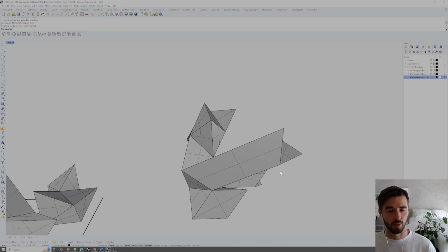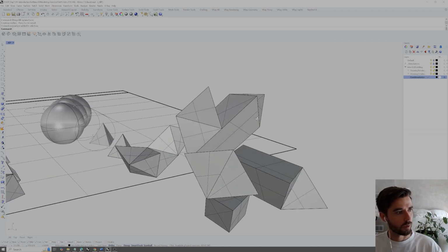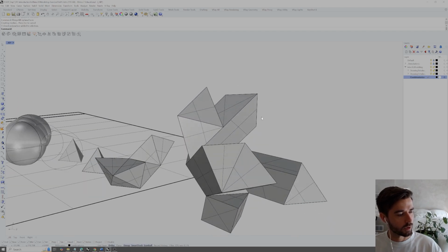It doesn't really know whether or not those do overlap or not because they align so perfectly. So just go ahead and go one by one, and whenever it fails, just do a different set of 2. It's totally fine. Eventually you should be able to get all of them Boolean together. And as you do get successful Booleans, remember to just merge all coplanar faces. So we now have that all merged together.